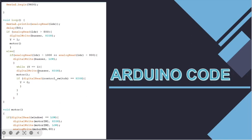This will be actually our main code, and this delay is given for the Arduino to take the value after this time interval, and serial print will be showing the value of the resistance of the LDR in the serial monitor. Firstly, if the value of the LDR is below 800, the buzzer will be high, and y will become 1.